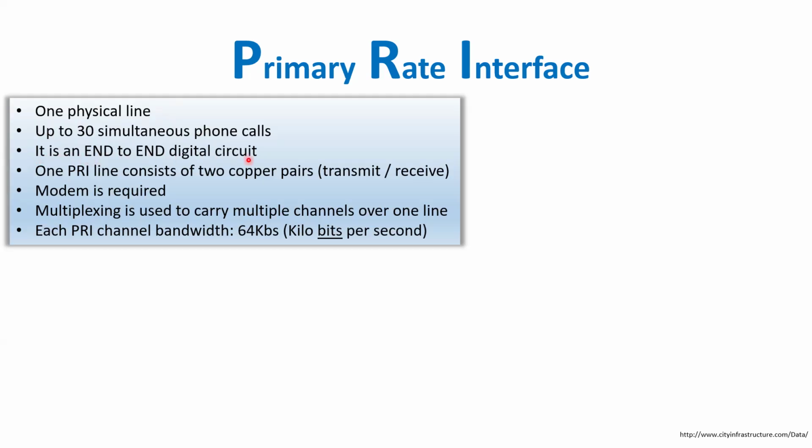It's an end-to-end digital circuit, so it's almost like the Ethernet type of cable, but it just goes much further. Basically, the telephone conversations are multiplexed, modulated into different channels, and those channels are transmitted through those 2 pairs. On one end, it has to be modulated into those 2 pairs, and if you want to receive one-to-one conversations, you just have to demodulate that on the other end.